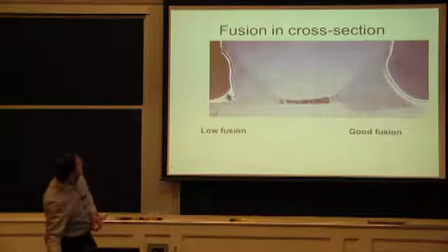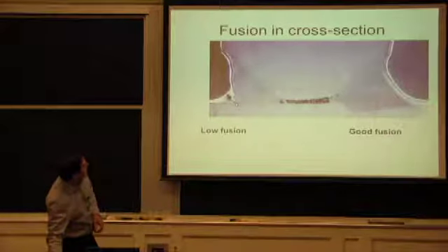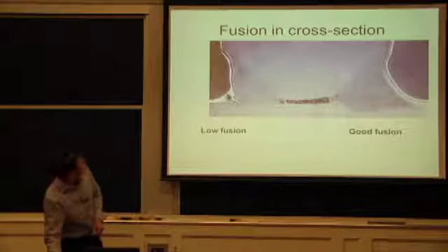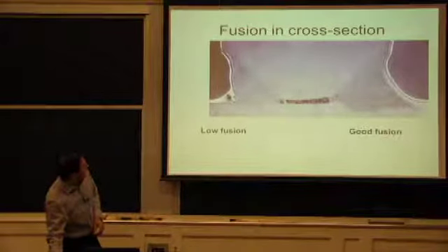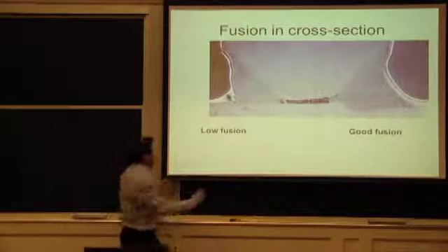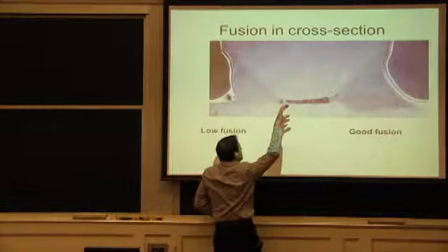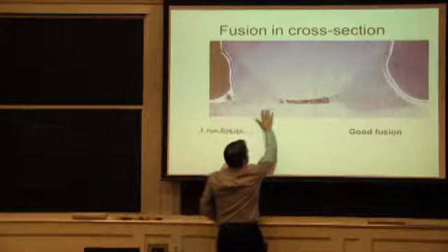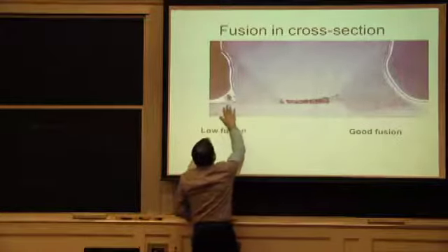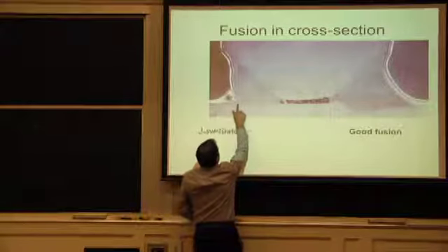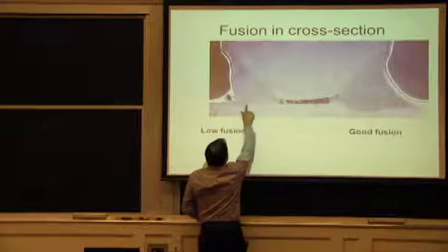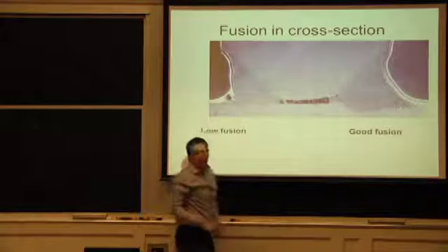And we had some cross-section views of this. You can see on this side the contact angle, between this location and this, is less than 90 degrees. And you see the interface right here. So it's not fused. This is the diagonal that has a little bend with a flat portion to be welded, and you have this lower chord of the joist. Right here you have a little bit of grab, but if you start cracking right here, it will pull right off.